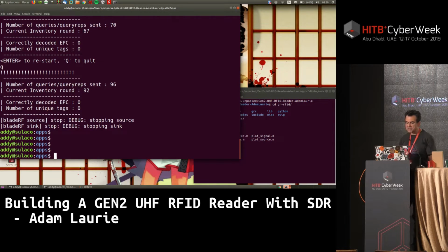A couple of major lessons I learned there. One is, for some reason, under Linux, certainly under Ubuntu, they're still using libbladeRF 1, which is the first version of the BladeRF library. And there are some really horrible bugs in there. Basically, the way a BladeRF works is it has three stages of amplification. And when you set your amplitude in your Python GNU Radio software, the libbladeRF library handles that for you. In libbladeRF 1, it seems to be somewhat random.